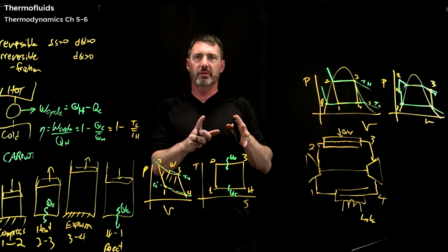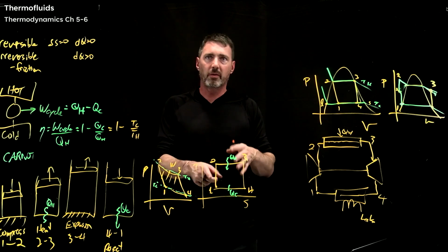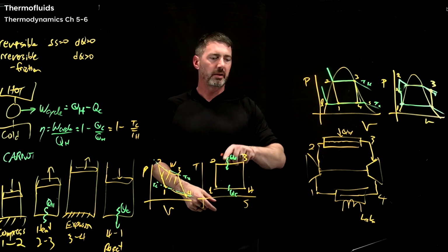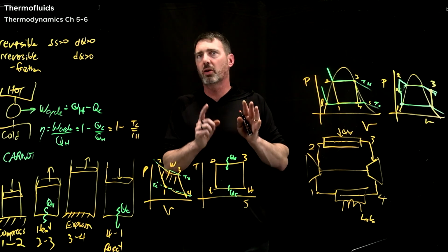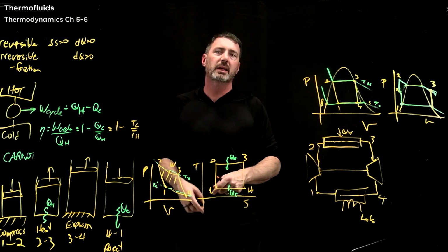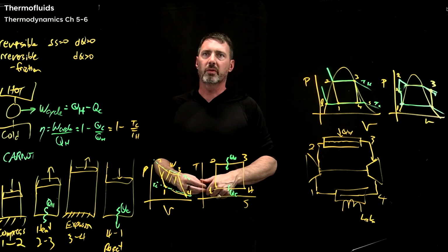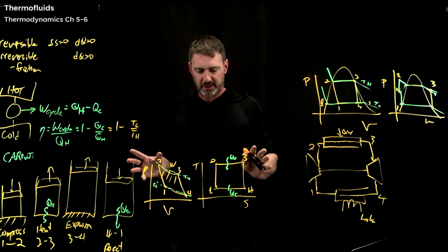Usually what people end up doing, you sort of draw the TS diagram. You can kind of solve all the pieces there in the TS diagram. You would draw sort of lines of constant pressure on the TS diagram so it's complete. And then you would just kind of work through and solve it. So I'm going to erase the screen. I'll be back in a second.